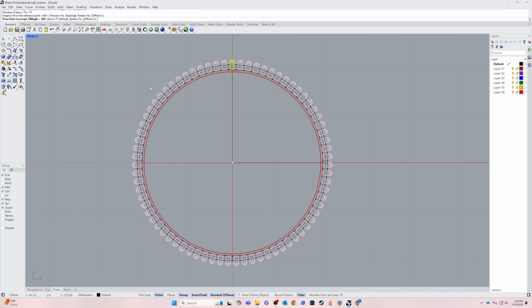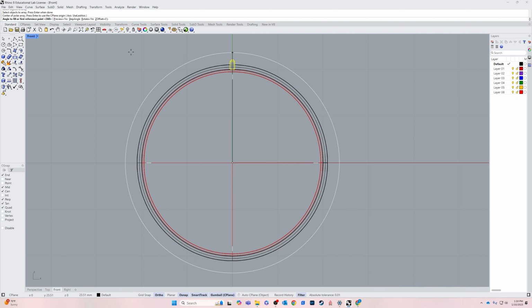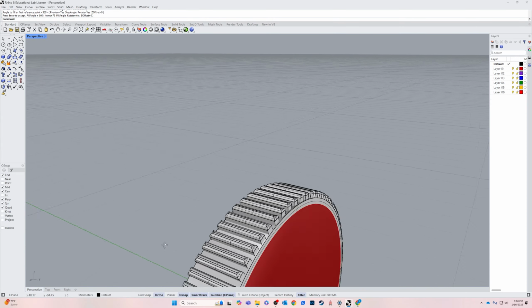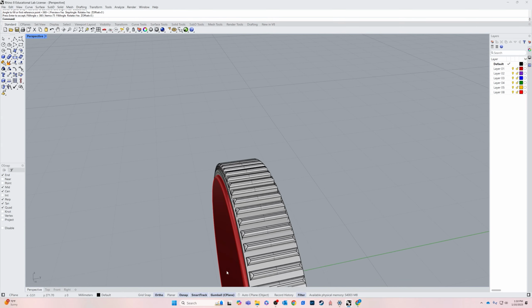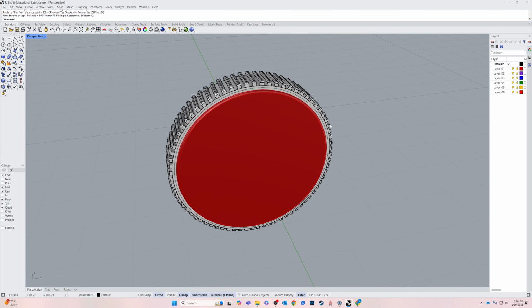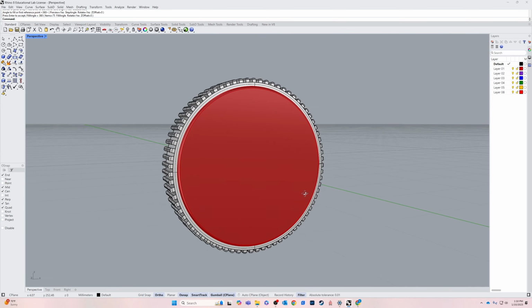And then it shows me a preview of it. If I've got it wrong, I can go escape, enter, click on it again. And I can up the amount or whatever, enter 75, 360. I think 75 looks great. Enter, enter, enter to get out. Once it's black, you know you've got it right. And now we've got all of those objects arrayed around the center object there. So a little complicated, but it works.